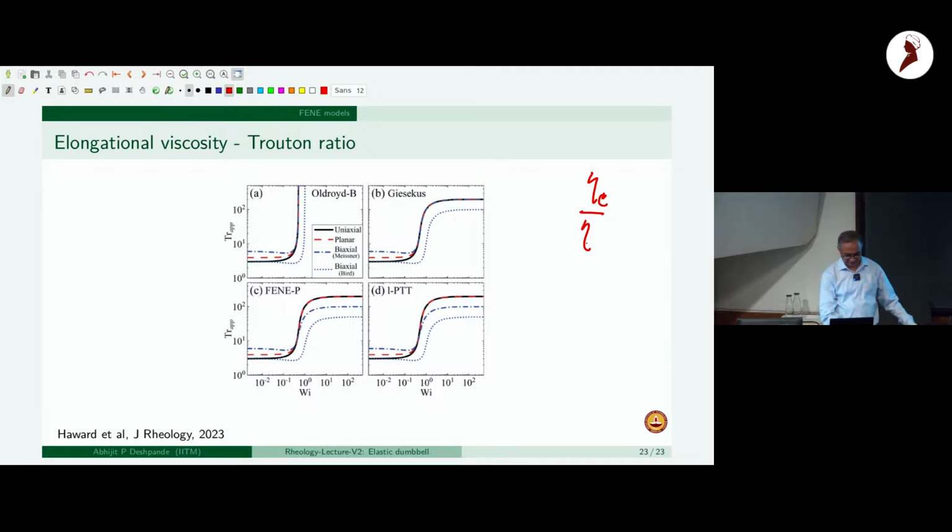So you can see that it starts out from 3, but even the Oldroyd-B model gives you this diverging viscosity. So in shear, it shows a viscosity which is constant, but in extension there is a diverging viscosity. This is seen both in real material, which shows no reliability. If I do shear characterization well, I cannot predict what's going to happen in extension, and models also similarly show